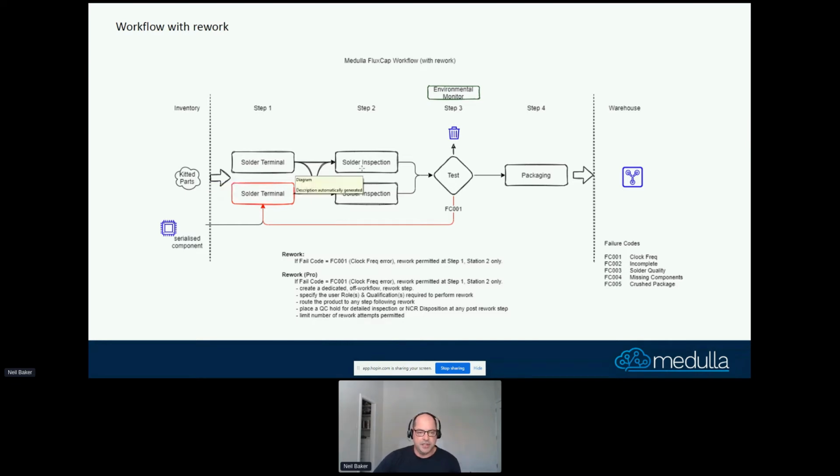You've got a QC inspection, you've got a bed of nails tester, and then perhaps just some manual assembly. That whole production line will operate in a series of events that typically are managed quite often with a person with a clipboard and a piece of paper, and that piece of paper then follows the product as it goes through the production line.